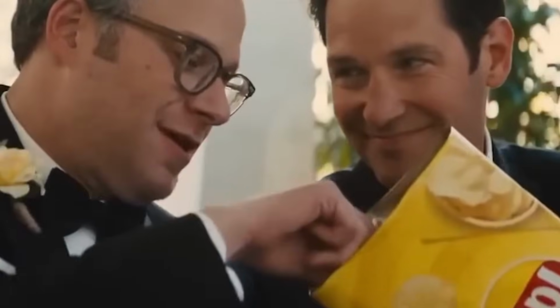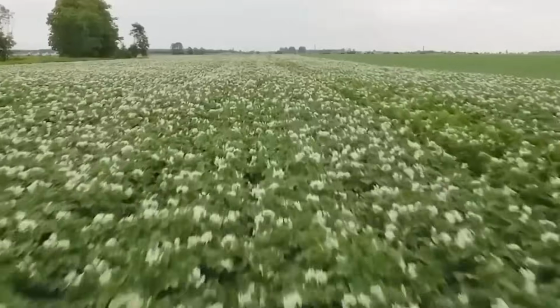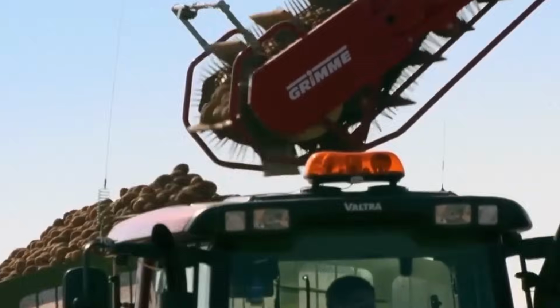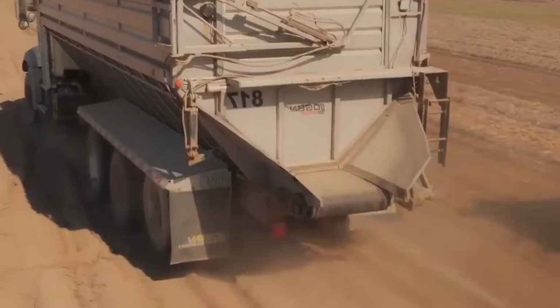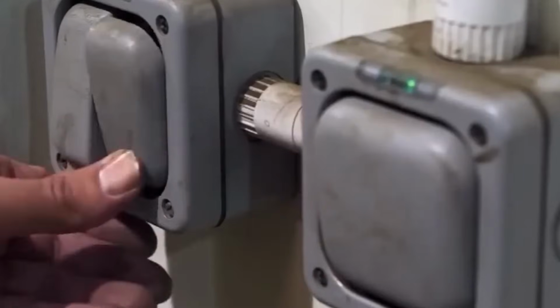The speed of both the impeller and cutting head is synchronized to maintain consistent thickness regardless of potato size. Slices exit the cutter in a continuous stream and are immediately passed through a water flume to prevent browning caused by enzymatic oxidation. The sliced potatoes are then subjected to blanching. This step involves immersion in hot water or passage through a hot water curtain at 65 to 75 degrees Celsius for 1 to 2 minutes.